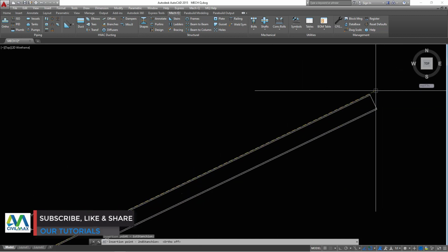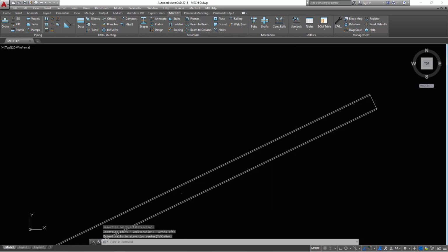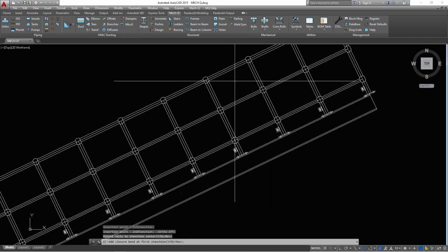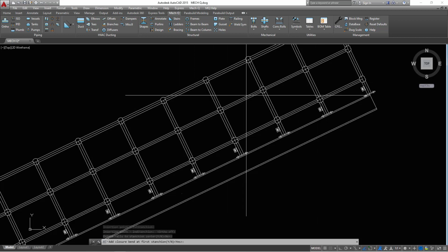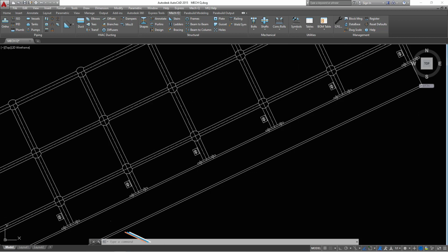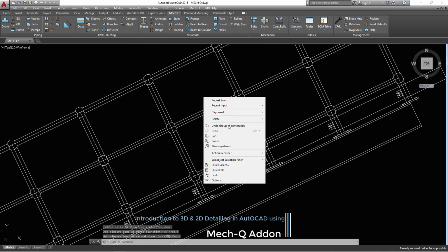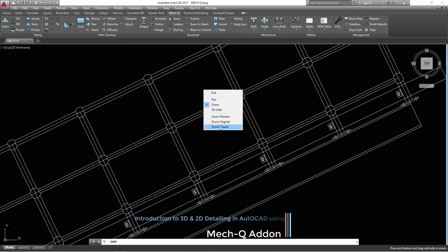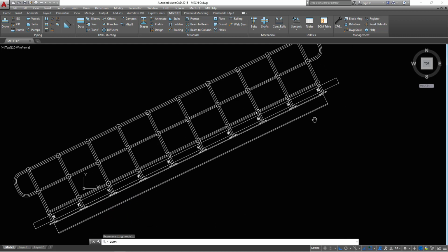Let me just drag that aside and try to place my parameter on that spot. Right click, and we can see the handrails have been generated, but this is not the appropriate handrail we need, because they're not matching the slopeness. They're not matching with the stringer slope.